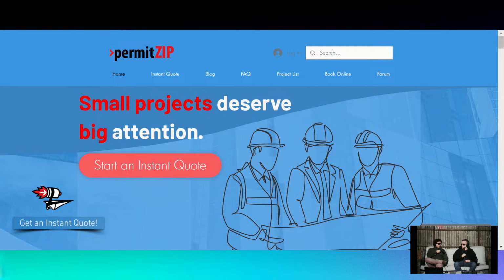or we're told it will be insulated and they end up not being insulated, or a skylight gets added we didn't know about and the equipment's already been purchased, or the programming changes, or somebody wasn't completely truthful about how the space is going to be used and they're expecting twice as many people. Yeah. Or maybe they're not following their occupant schedule. There are way more than 1,000 things that come into play that make that educated guess be something that's not going to work. At the end of the day, if you're asking for HVAC tonnage to be reduced, be ready for your comfort to suffer.